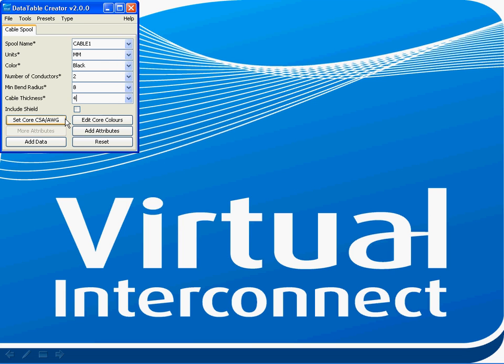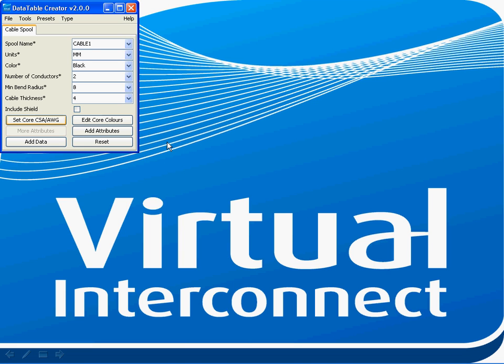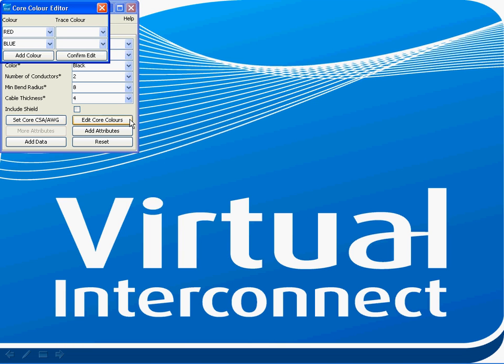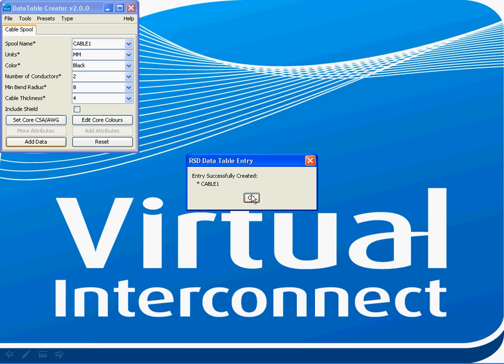Now I need to set the CSA or wire gauge for the conductors. I'll choose wire gauge and a value of 16. I can now choose the core colors. I can select them from the drop-down list, or if I want to, I can add my own values. Once I'm happy with the values I've got, I click Confirm, and then complete the process by clicking Add Data.